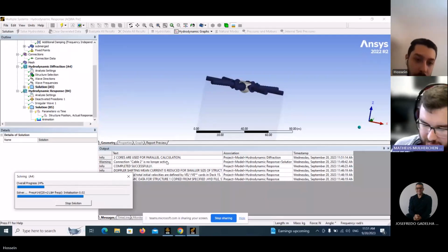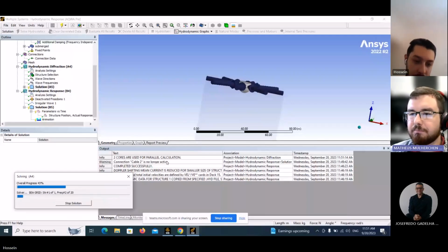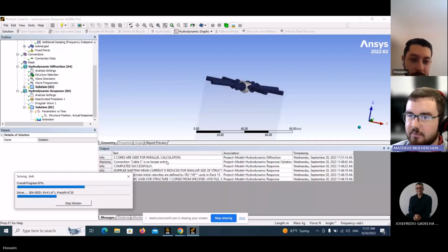Let me ask you something that is way back there about the geometry again. One question that I have is, you calculated the inertia values based on the formulas for the geometry, right? Yes. So my question is, those formulas assume that the geometry is a solid, but the actual device is like a sheet shell of steel or something like that. So doesn't that interfere with the results and invalidate them?